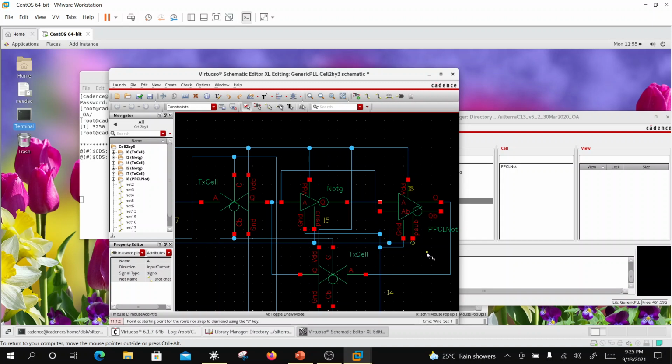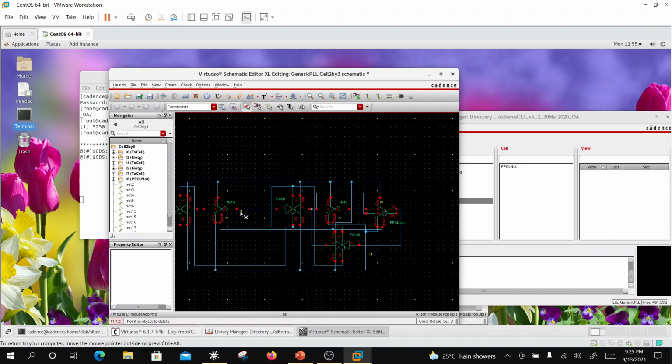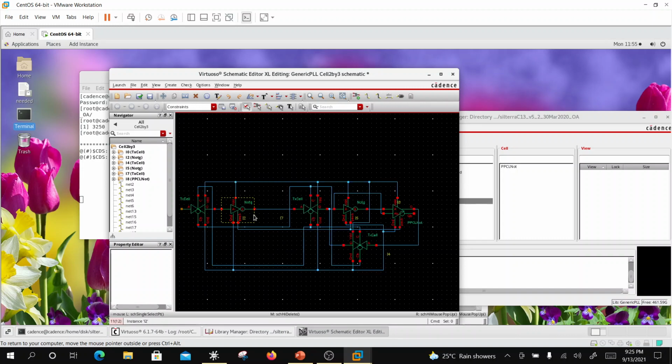So delete, and clean up this guy, and this guy, right? And now see what has happened. Okay, now I'll show you what has happened. So we got rid of one gate over here and a feedback path. We still have that. That means polarity here is reversed. So this node is a Q and this node is a Q bar, right? So this is a Q bar, okay? And this is Q. So I need to feed it back with a NAND gate.